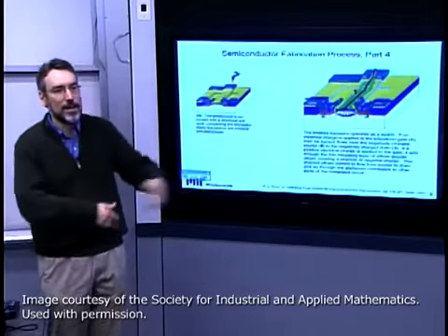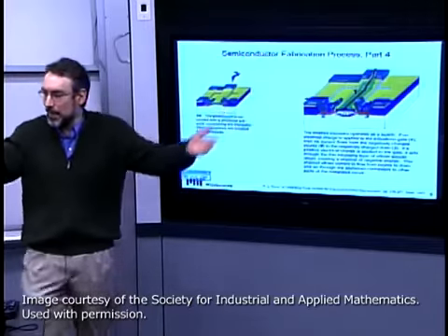It's always a deposit everywhere, because you can do that in parallel across the whole surface of the wafer, and then have to go back and do a subtractive process to typically remove what you want. There are very, very few steps where you can selectively grow or selectively add material only where you want it. Okay, so that's an example of a huge constraint in semiconductor processing.